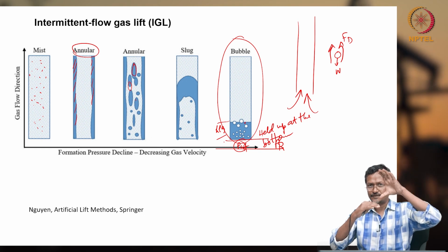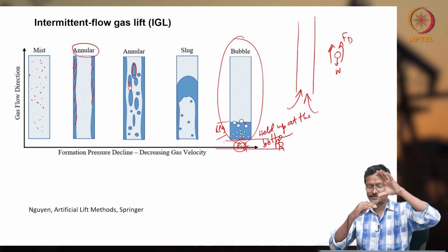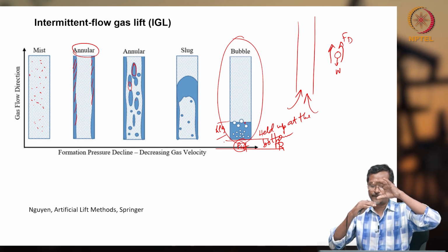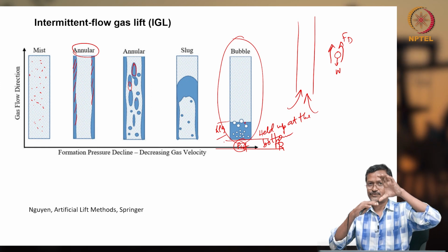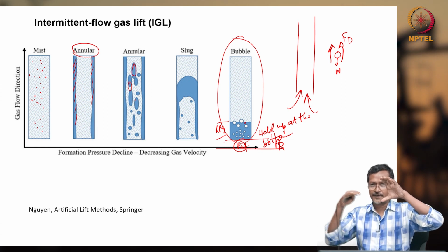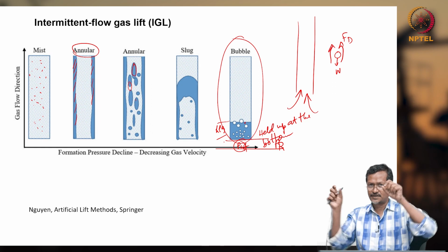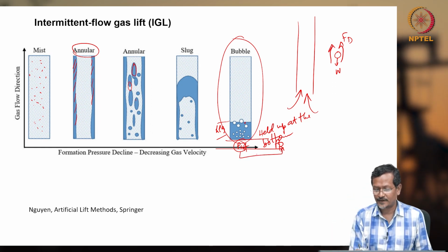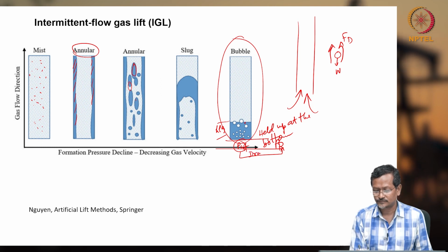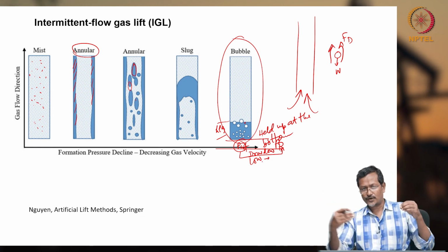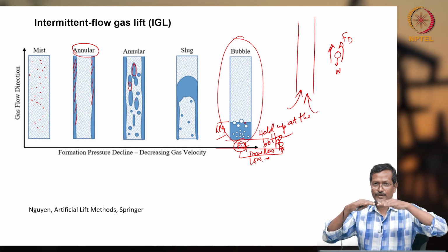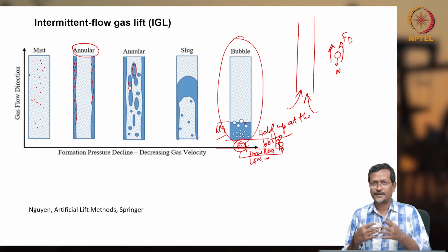When H increasing, that means PWF is going to increase, so your flowing pressure is increasing actually. So, flowing pressure increasing, PR certain amount is there, flowing pressure increasing, the difference will be very low, okay. When PWF and PR difference, or drawdown, is low, new fluid will not come into your wellbore, okay. So, in that case your gas or liquid entry into wellbore will be stopped. So, you will not get any production.